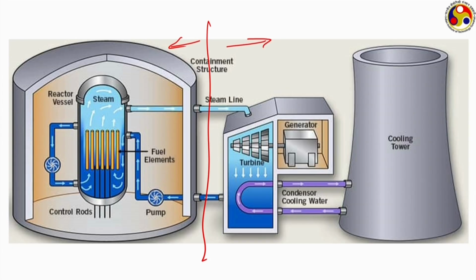Here is another point of interest to note: the control rods in case of a boiling water reactor are mounted below, whereas in case of PWR they are mounted from the top. As in case of boiling water, the upper part of the vessel is covered only by the vapor phase. So, there will be no point using the control rods there; rather it will be much easier to control the reaction if they are inserted from the bottom side.